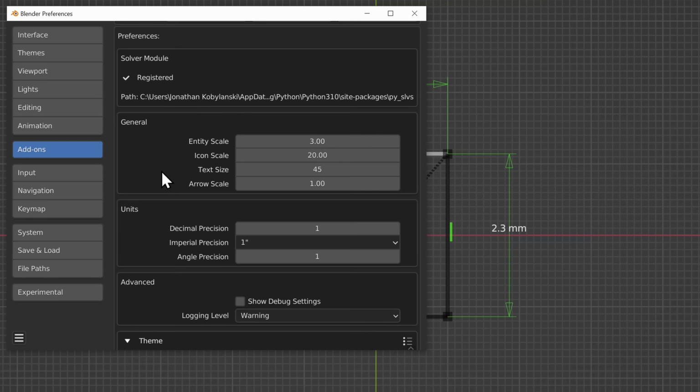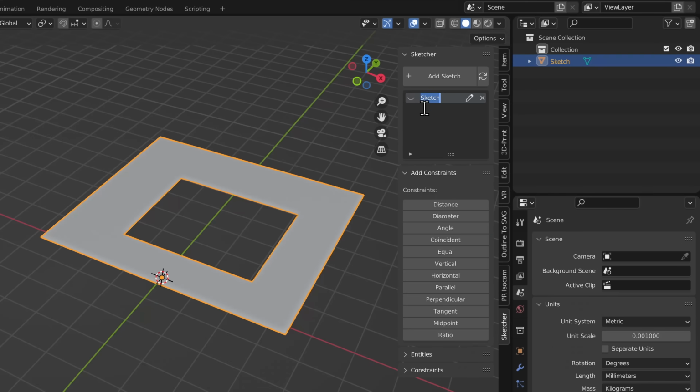There's also less obtrusive dimensional arrows. There's also scaling for these arrows to make them bigger, not the line width bigger, only the actual size of the arrows. Then we've also fixed a little name bug, which was that the name wasn't renaming the solid, the mesh that was being made, when you renamed the sketch.